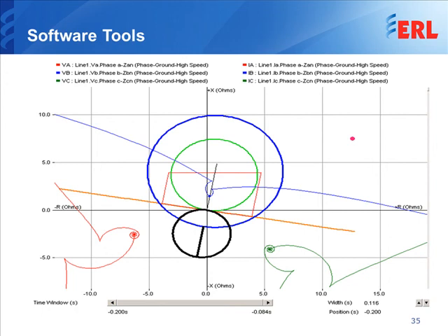So we know this fault is on B phase, and it's about 20-30% of the line. Usually the first circle there is about 80%, and in this case we have just inserted the quadrilateral characteristic for the first zone, but this could also be replaced by a Mho circle, which is the circular type. So this tells you that the fault was a line-to-ground fault about 20% of the line, and this could be determined by the fault locator algorithm that a relay or a microprocessor DFR will tell you.